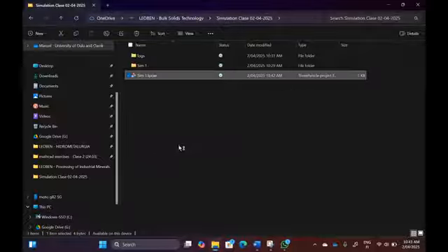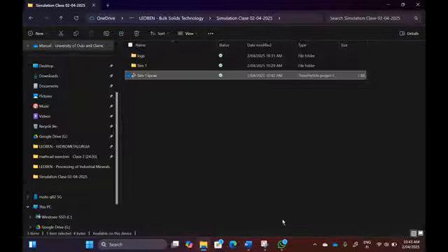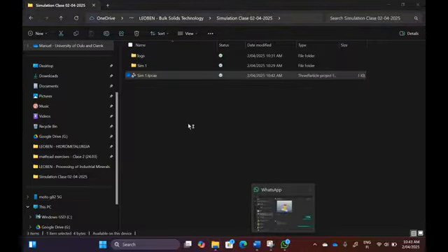Change the working directory. Just follow me, okay? Click on File, Working Directory, and change it to a valid folder, which means no special symbols, not too long a structure. So if you click here, it should not be infinitely long. Scenario, something like C, simulation, a rather short name.